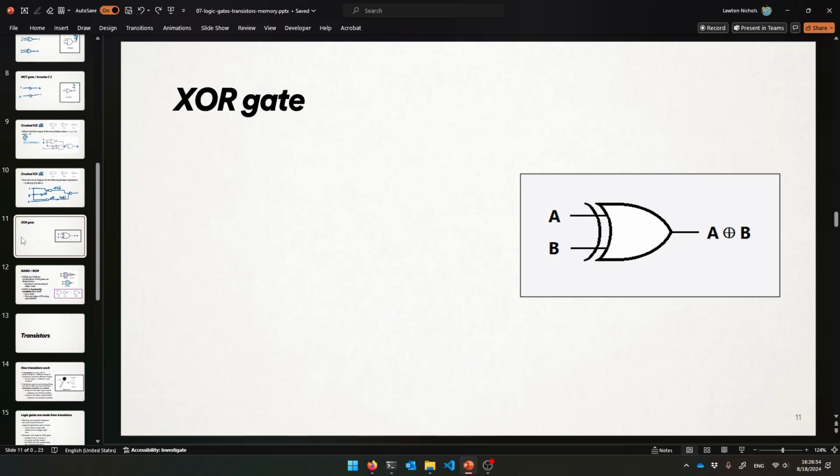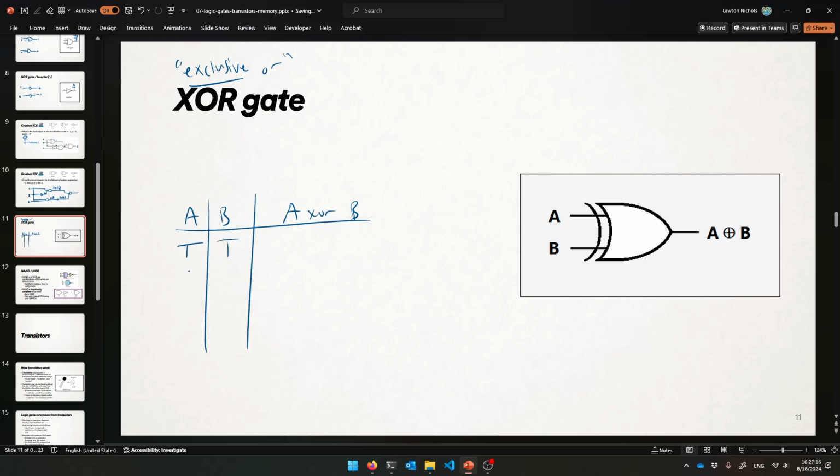All right. I taught you about exclusive OR. Remember that one? It's XOR for short, so it's short for exclusive OR. And it's like regular OR. I'll just do the example again. So let's do the truth table for exclusive OR again. So A exclusive ORed with B looks like this. So true, true, what are all the possibilities? True, false, false, true, false, false. So it's like OR for all these guys. True, true, still false. But it disagrees with normal OR, which is also called inclusive OR, for the double true case. It considers that to be false.